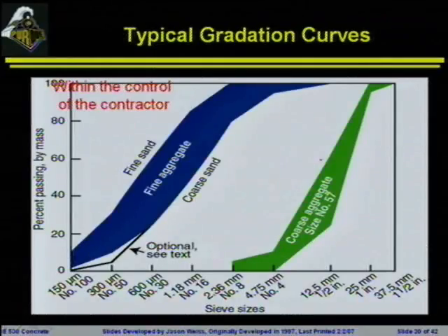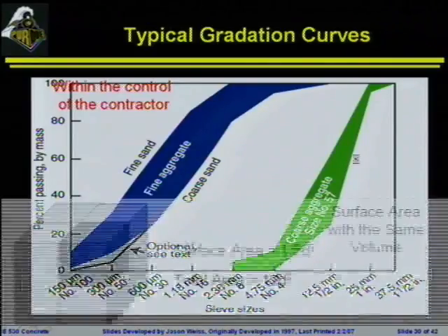Again, here are your typical gradation curves. So you can see that there's a little bit of flexibility here. You can and should be tightening up these specifications if you're running quality control, and we'll talk more about that when we get to this.